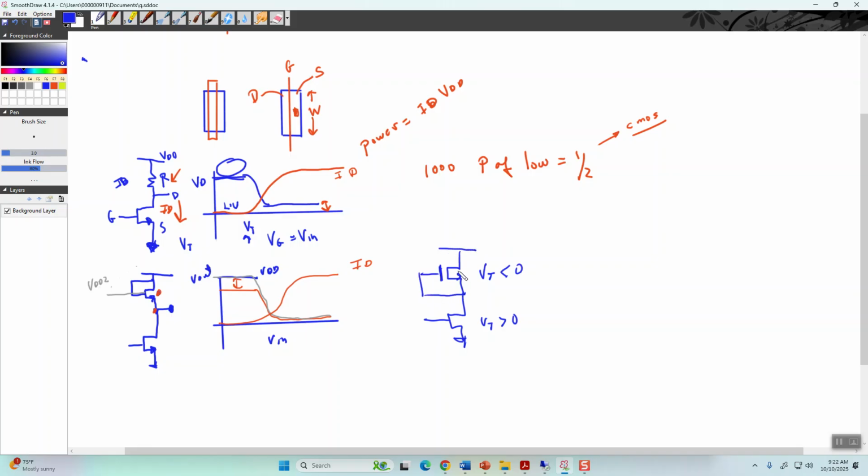And so now you're getting a rail to rail with only power and ground. And it was very fast because both of the NMOSs have electron mobility in the channel, which is higher than PMOS, right? So you can make some very fast chips this way.